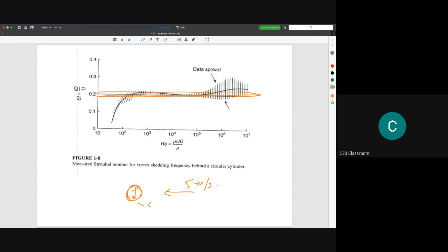Normally in fluid mechanics research, we will convert the velocity into the Reynolds number. If you stick with 5 meters per second, you could draw a graph with velocity on the x-axis, 0, 1, 2, 3, 4, 5, 6 and so forth, but your graph is only specific to the 5 centimeter condition with a certain velocity.